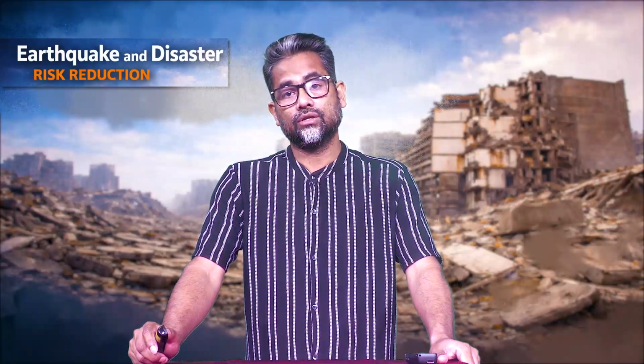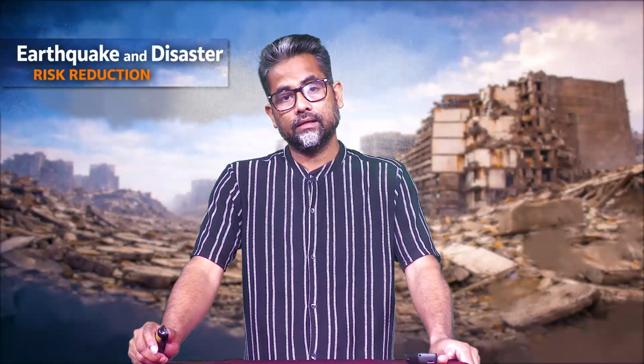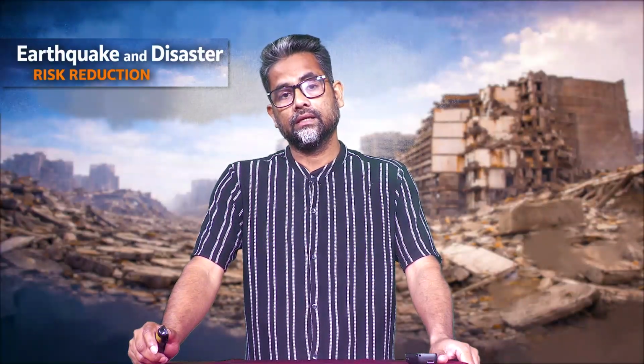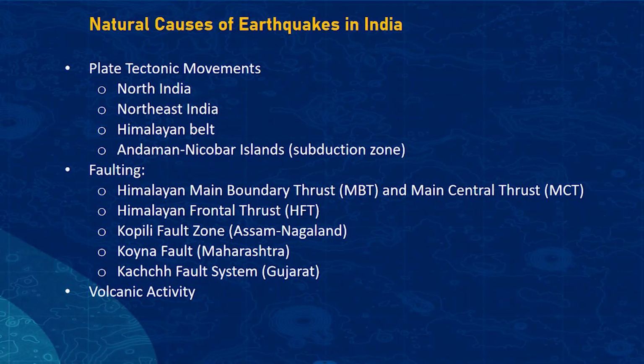Faulting: sudden slip or movement along pre-existing faults releases stored elastic strain energy, causing the ground to shake. Faults can be reverse or thrust, that is compressional; normal, that is extensional; or strike slip, that is horizontal. Major active fault systems in India include the Himalayan Main Boundary Thrust, that is MBT, and Main Central Thrust, that is MCT, known as primary zones of convergence in the Himalayas.